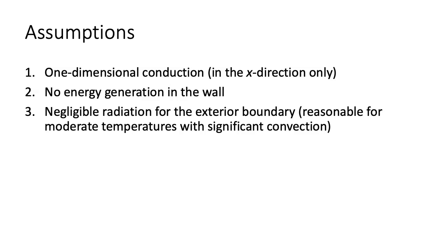Our first assumption for this problem is one-dimensional conduction in the x direction only, which is based on the information provided in the problem statement. Our second assumption is that there is no energy being generated in the wall, which is again based on the problem statement because it does not include any indication of internal heating.